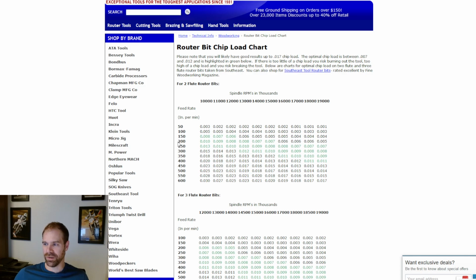And this is the part over here that really matters. I've run as high as 250 or 300. It really depends on the setup of the machine, but for this purpose, we're going to do 200. And for the machinists out there, especially machinists who have done work in aluminum and especially steel, this is going to sound very fast, because it is. This machine is going to haul through the wood. That's just the nature of wood router cutting: you've got to go fast. It really is the best way to do it.